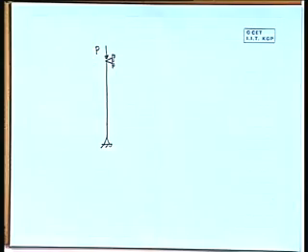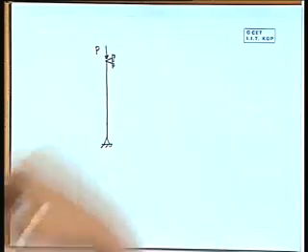So, it is so long, I have just shown it with a line. If there is a load P, what will be happening? If it is acting absolutely along the centroidal line, P by A will be the stress like a short column, and it will take up to what range? Up to the P by A value being less than or equal to your allowable stress.